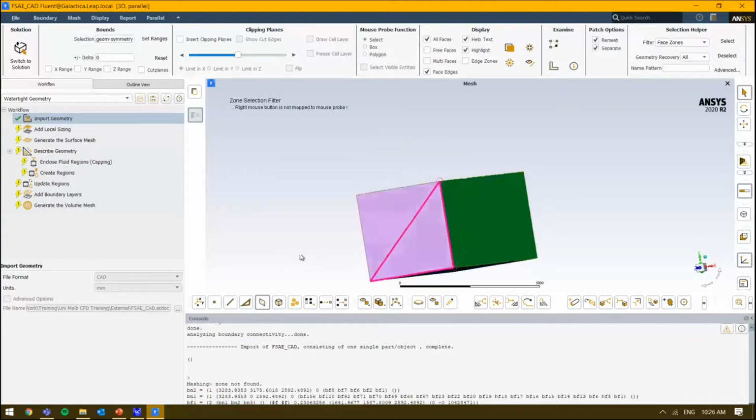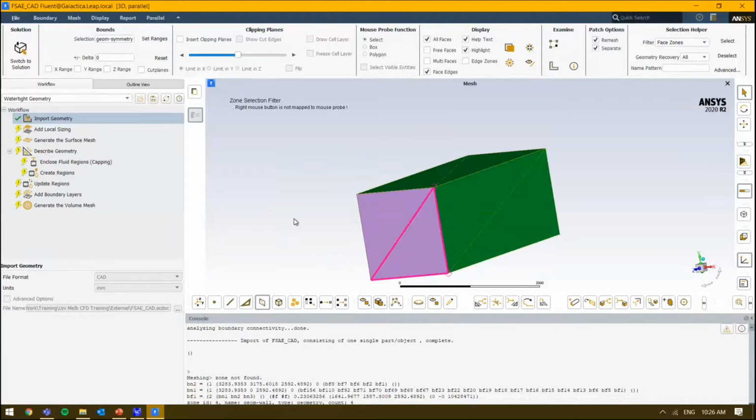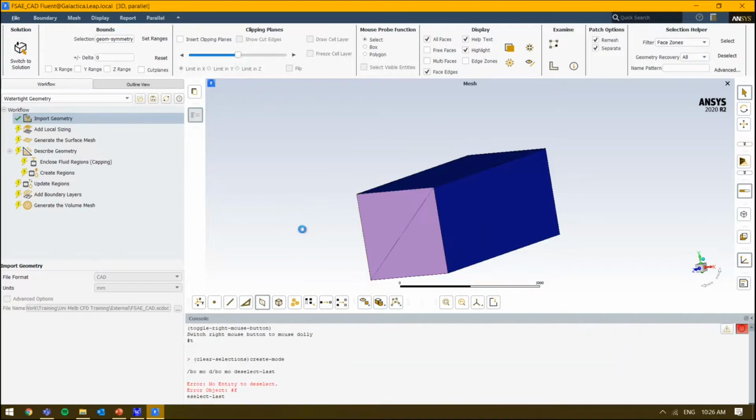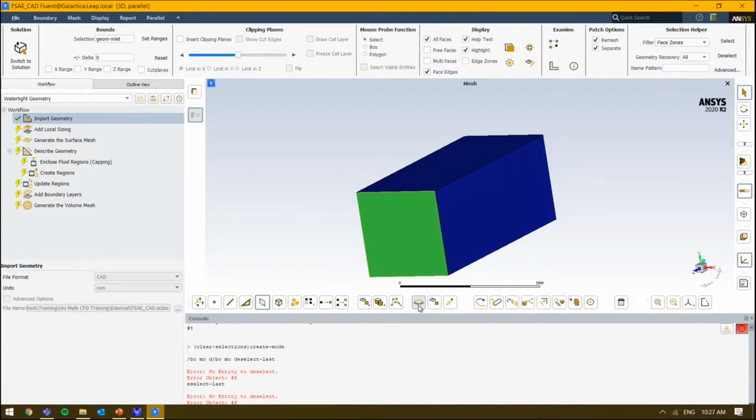That's one for symmetry. I've got some additional tools in here. So if something does come to you and it's not exactly the way that you want it, you can actually do so. If you've got something selected, you can hide certain components in here, rename, isolate. You can even do things like remesh, separate them as well. So if you've got something that's tied together, you can actually separate them, then rename them, making your own name selection, things like that. All these things are doable inside Fluent.